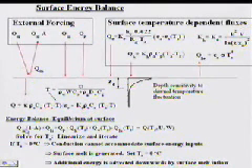And then I'm going to write the energy balance equation at the surface, and I'm going to specifically note which of the terms depend on surface temperature. The sensible heat flux, the latent heat flux, the outgoing long-wave radiation, and the conduction into the snow depend on the surface temperature through this equation we've constructed here, and the energy content as well as the snow water equivalent, because they give you the temperature from the primary state variables of the model.